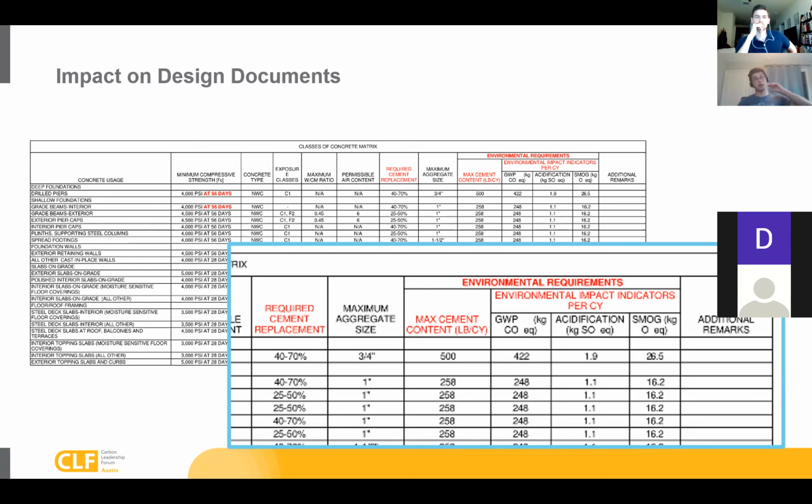But in addition to the concrete changes, it's more common, especially in the US, for these long span stadium roofs to have a planar truss. And for this one, we used a cable system, and it's less common here because it's a different erection sequence, and it's just not the standard of practice, but it's not totally unreasonable.